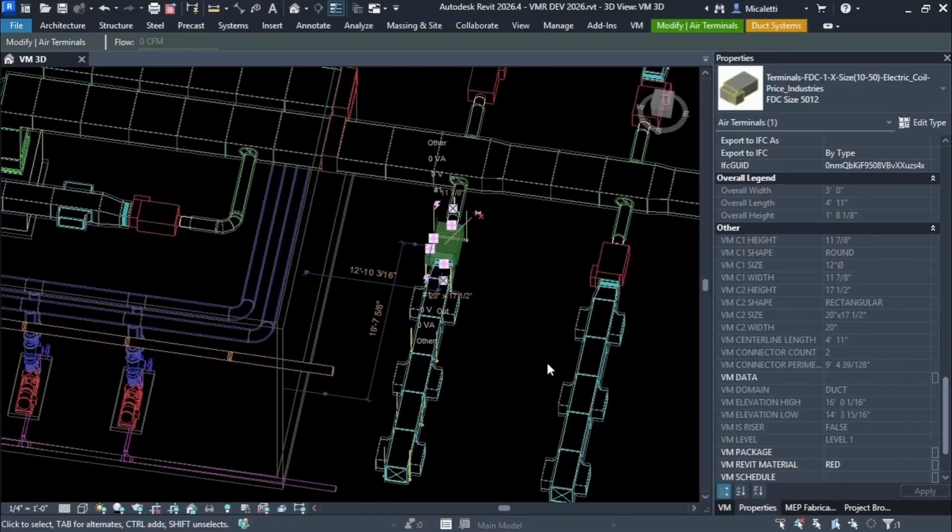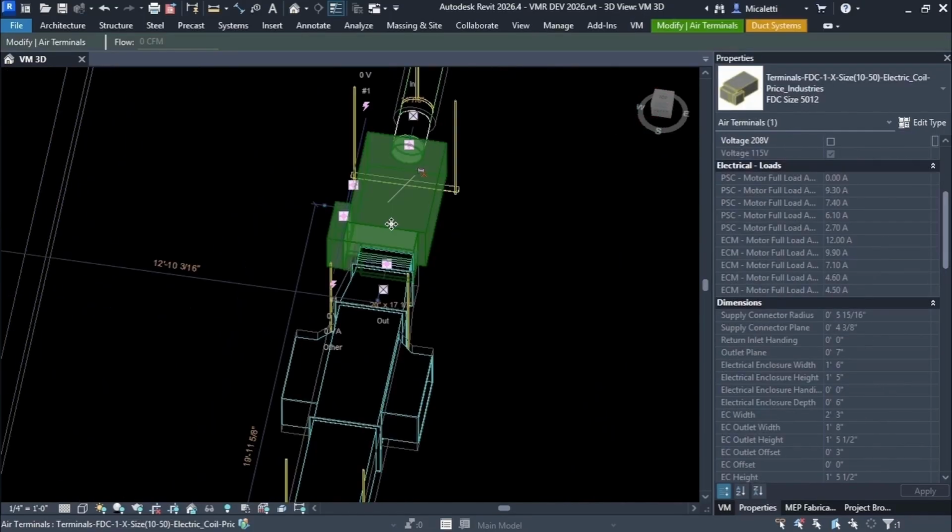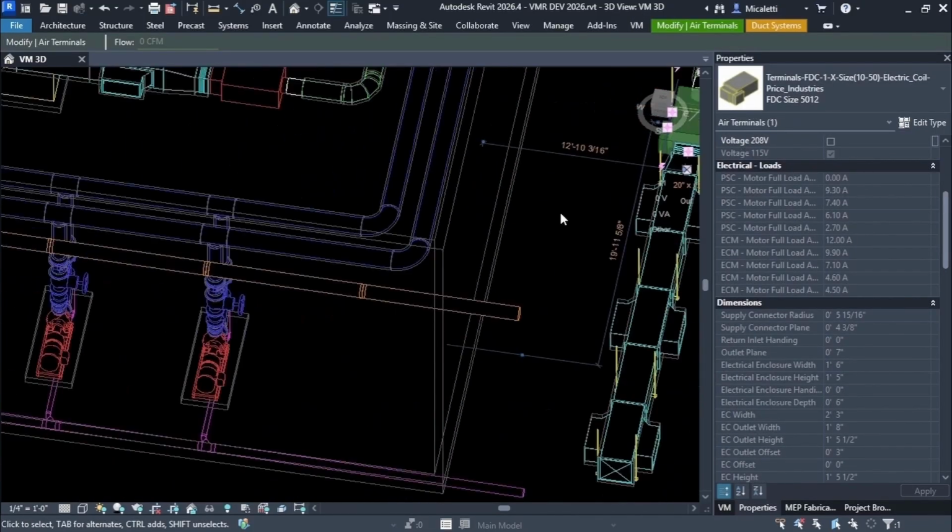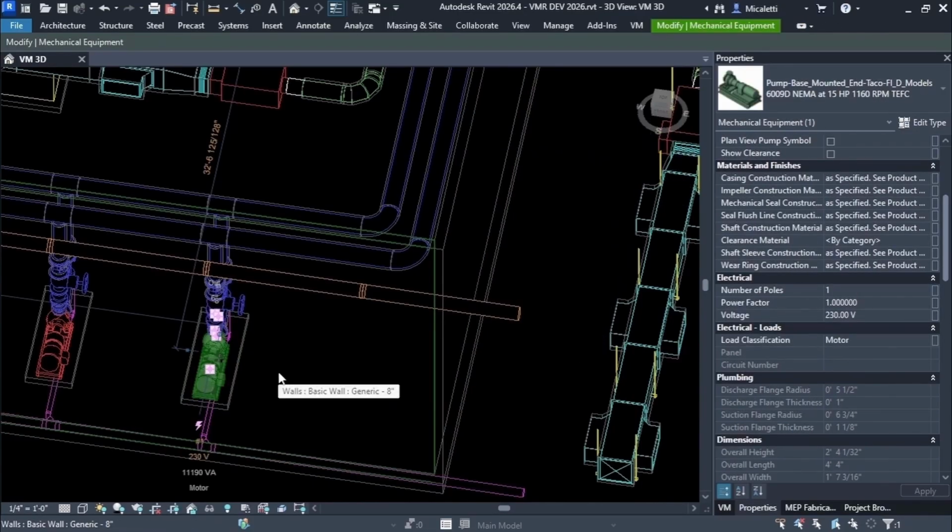And this is really confusing to people. Parameter name, there's an underlying GUID, right? So the height parameter is not the same height parameter throughout Revit, and they have to do this because Price needs a parameter called height, and Taco may need a parameter called height, and these two manufacturers are not coordinating with each other and using the same GUID. So you have two parameters named height, but they're not the same.